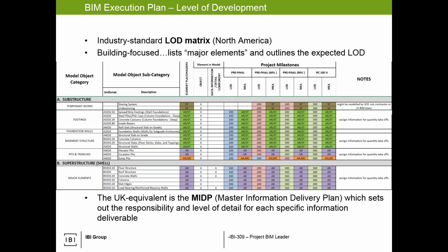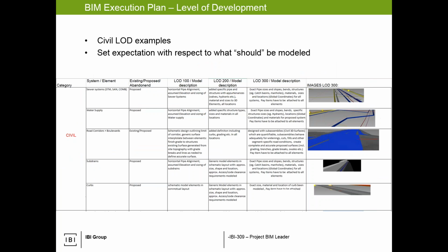The UK has an equivalent. It's called the Master Information Delivery Plan. Same concept, though. Who's accountable for what parts of the model, and at what stage of development will they be throughout the life cycle of the project. And again, we're working to have a proper template of this that's available for BIM leads to grab and augment accordingly.